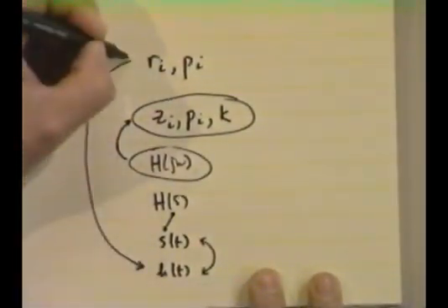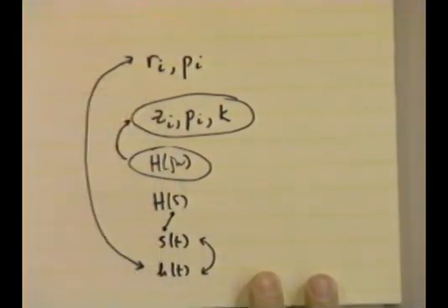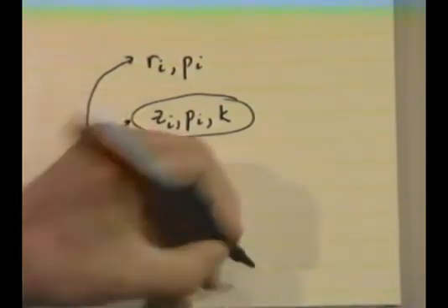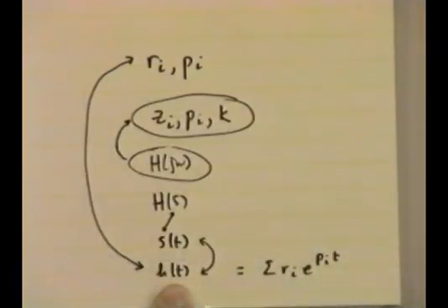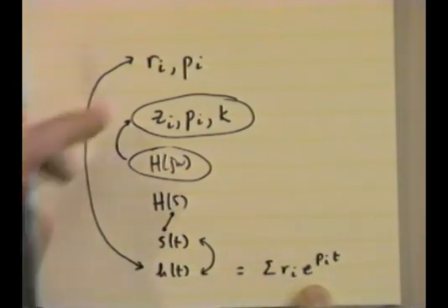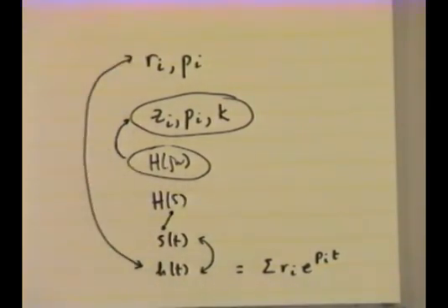The connection between the impulse response and the residues and poles is really easy because h of t is equal to the sum of r_i e^(p_i t). And here, I'm assuming, to make it simple, that the poles are distinct. They're not repeated. Otherwise, we have the t e^(p_i t) terms and t squared and so on, right? So some of the connections here we've made very nicely, and a few of them we haven't.